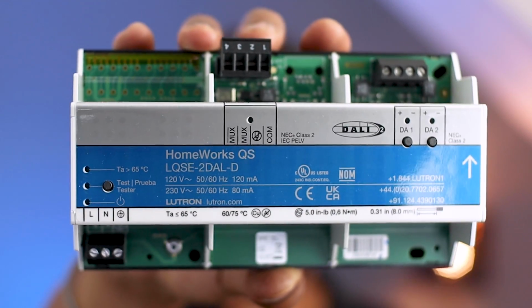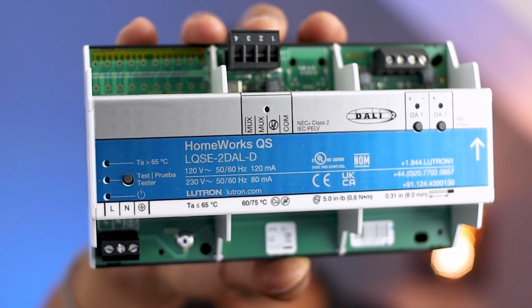We need to remember that the DALI zoning, as we call it, can only be set up, changed, or modified by the Lutron commissioning engineer. It is not something the end user will be able to change by himself. And also, if you need to control more than 16 lighting zones, you will have to add another DALI loop, even if you haven't reached the maximum of 64 DALI drivers on your first DALI loop. In this tutorial, we'll be using the Lutron DALI module as our DALI controller.